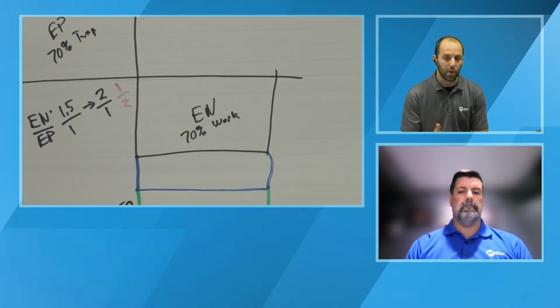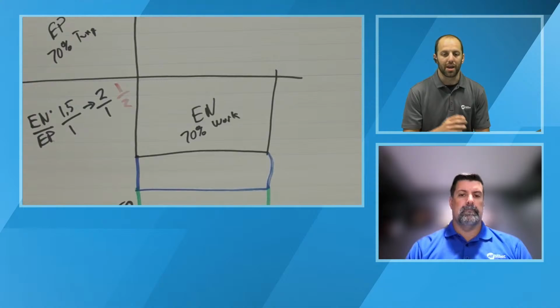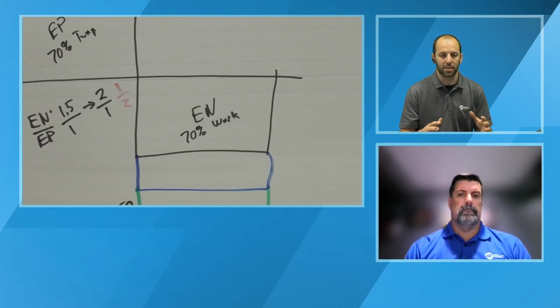If you're doing low amperage applications, a ball, as we saw in the drawings, can negatively impact you. The arc wanders around and you don't have good arc stability. But in high amperage applications, you have a lot of arc pressure from the amperage being generated and output on the torch, so you get a natural stability from that. In many cases, with more amperage you probably want a little bit larger weld anyway. If you're doing an overlay, you're trying to get a wider weld so you can get more material, or if you're doing a thicker section, you often want a larger weld anyway.